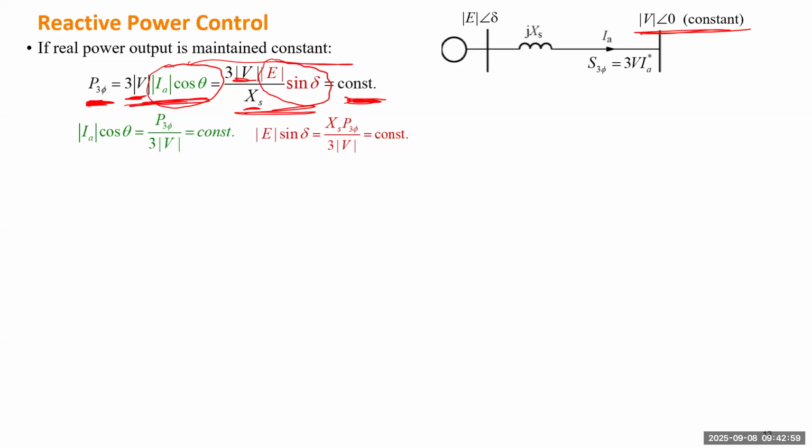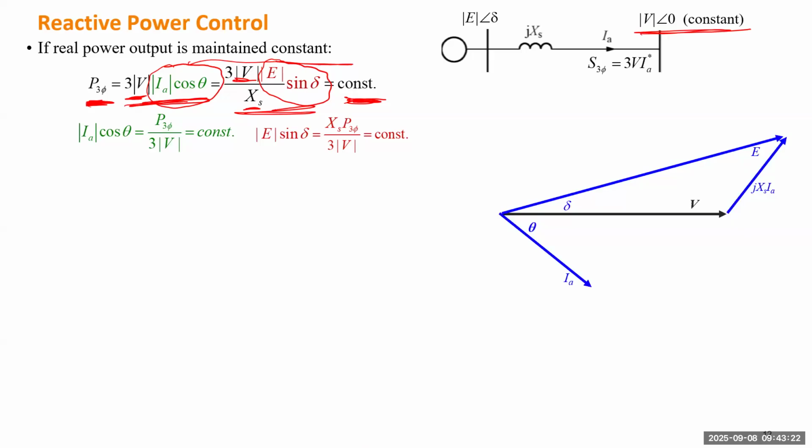to utilize the information on which to be constant, and we try to change the other variables along a certain trajectory that doesn't violate the requirement of being constant. So we start from V as a reference. This one will have constant length and constant angle. For this case, it will be 0. And we just draw the phasor diagram for one condition with current lagging voltage by theta angle. So this is a positive power factor angle, a lagging power factor.